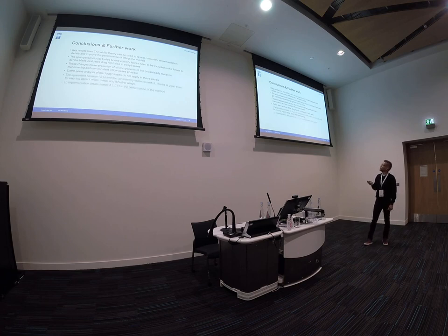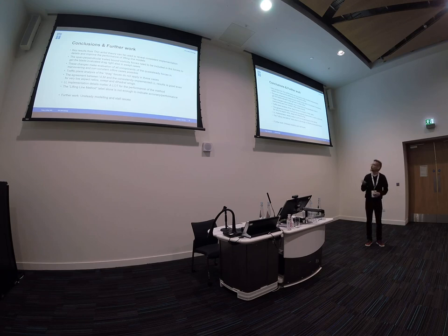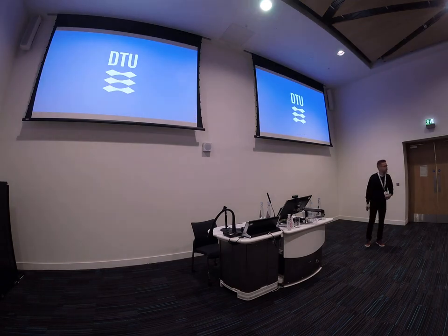Good agreement. And if you just make lifting line implementations that differ a little bit, you can get very different results. So when people say, we have made a simulation with our lifting line code, we're good, that's not necessarily the case. So that's the bring home message. Further work would be trying to tackle the tricky stuff when you have stall airflow data. And that probably finishes what I have to say.